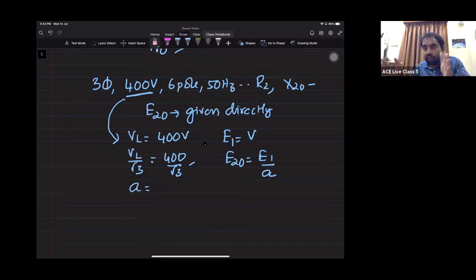That is the voltage across two slip rings. Like that, there may be some indirect information. If E2 naught is not given, that means the supply voltage may be given. From that, you have to get E2 naught. Once you have E2 naught, you can calculate all these values. I hope this is clear. Confirm me, all of you.